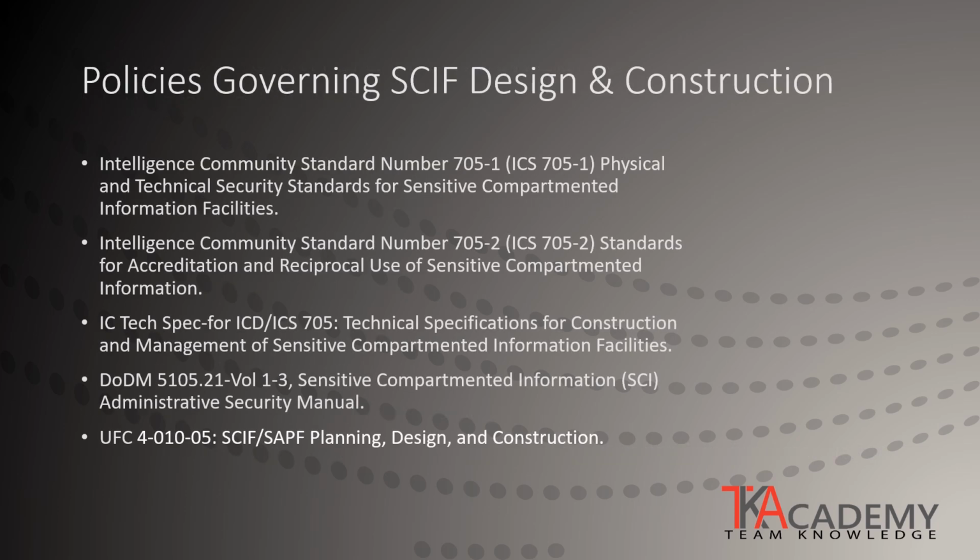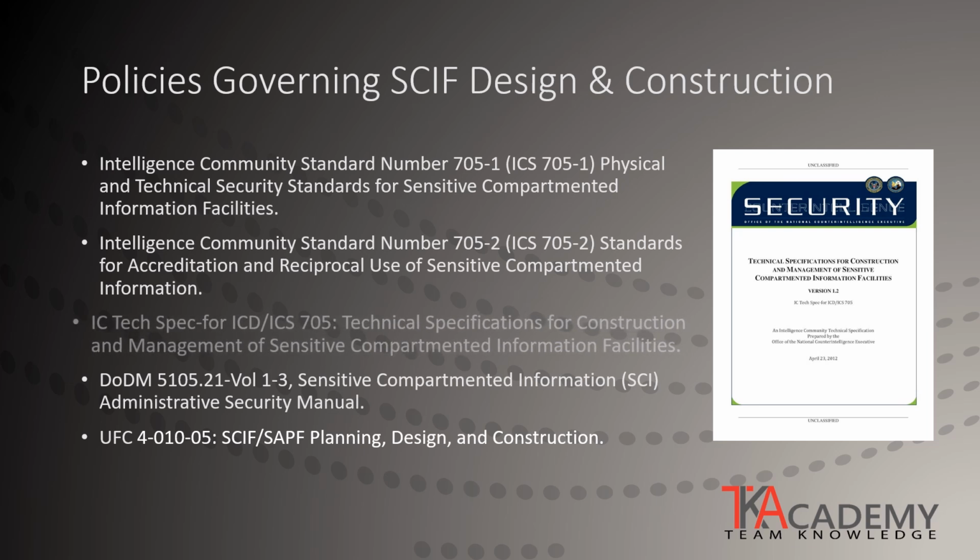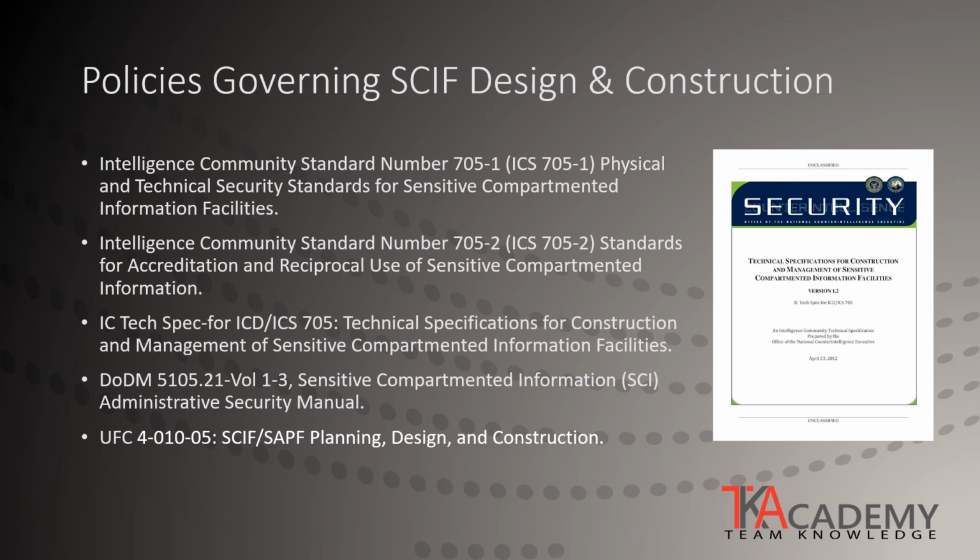As one could imagine, there are multiple policies and regulations governing SCIFs. Most of these come from the intelligence community, although the Department of Defense has also contributed to the regulations of the operations of SCIFs. The ICD 705 technical specifications for construction and management of sensitive compartmented information facilities has become the basic guide for governing design and construction of SCIFs. However, DoD has also developed a Unified Facilities Criteria, UFC 4-010-05, for the planning, design, and construction of SCIFs. These two regulations are very similar, but there do exist minor differences to be aware of.